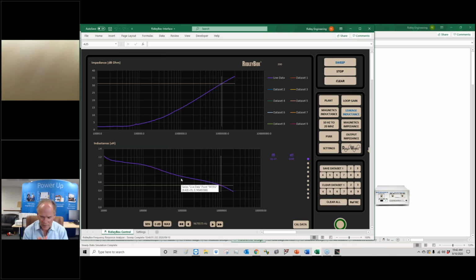So when I do pre-production runs, multiple samples, then I get parts back from the vendor, I run them all through this curve measurement, and I expect all these curves to be right on top of each other. They should all have the same characteristic. If they don't, they've changed my design.